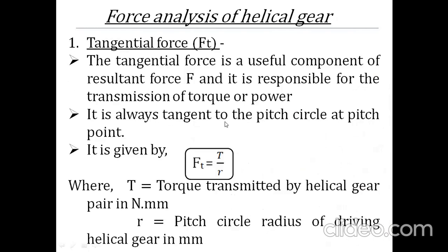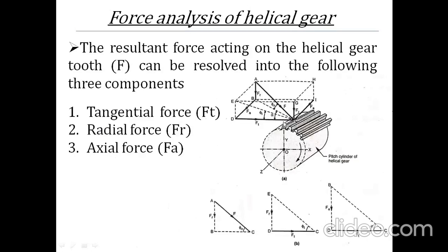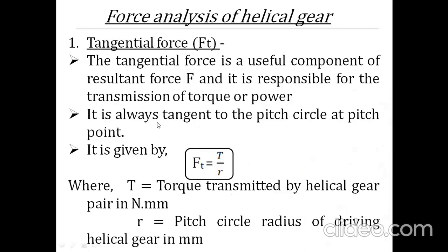Now, what is tangential force? The tangential force is a useful component of the resultant force F, and it is responsible for the transmission of torque or power. So here that is Ft, the tangential force. It is the component of the resultant force F, and it tries to rotate the gear. If the direction of Ft is from left to right, it will rotate the gear in clockwise direction. And it is always tangent to the pitch circle at the pitch point.